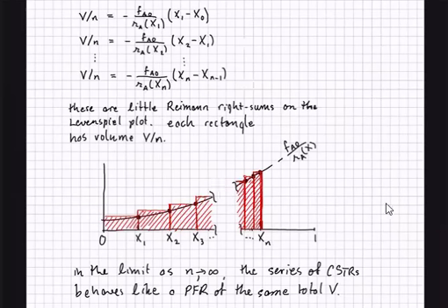Okay, so that's actually not so surprising. In hindsight, of course, the plug-flow reactor is like a bunch of little tiny volumes that pour into the next volume with no mixing across the two volumes. But every little plug is well mixed within. Okay, so that is a nice analogy, I think, that kind of gives you some intuition for how plug-flow reactors and CSTR reactors are related to each other. Comes across very clearly through these Levenspiel plots.